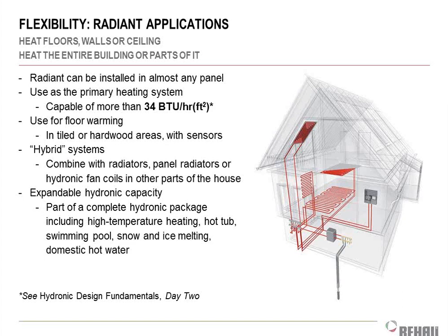You can mix and match your radiant floors with other hydronic systems. Like I said, you can have a hydronic fan coil or air handler doing some tempering. You can have the new part of the house on the radiant floor while the old part of the house may still have the old radiators. You could have your boiler servicing your radiant floor in your garage, but the rest of your house may have baseboard. There are a little bit different tricks on how we pipe it, but you can mix and match that kind of stuff all the time. And like we said before, you can do snow melting systems, which we're going to talk about in a little bit. You can heat domestic water with your boiler, all that kind of stuff.